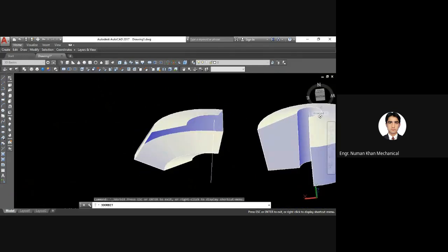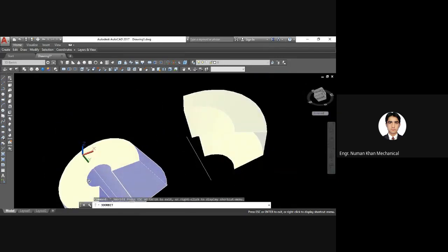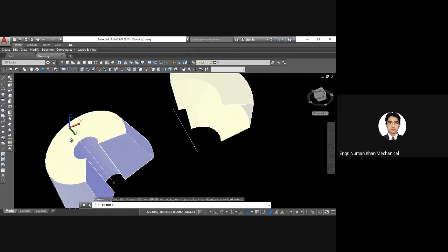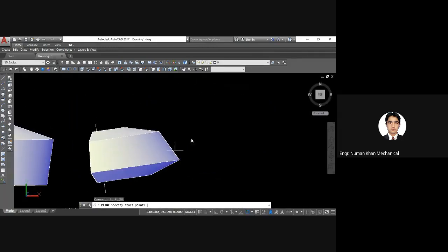Again, if you don't want a hole inside this object, for example, you want a cylindrical object which is not hollow from its side, you just need to define the revolve axis exactly at the edge of the object. For example, let's say I have an object like this one, to get a piston.